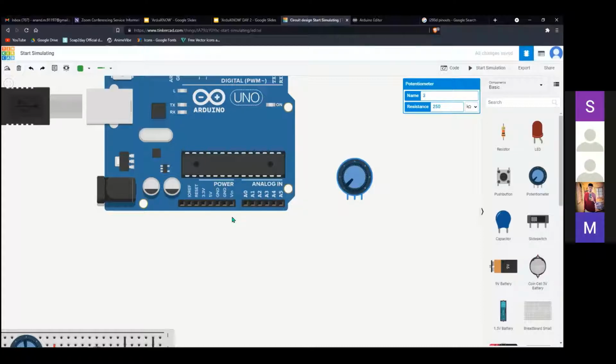To create the circuit, just hover the mouse on terminal 1 and click. It will start to trace, and there are some helping guides, horizontal and vertical lines, provided by the tool to ensure a straight line in the circuit. This terminal 1 I will be connecting to 5 volt, and the wiper.